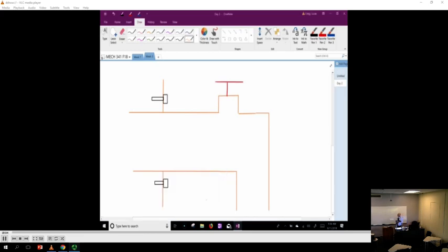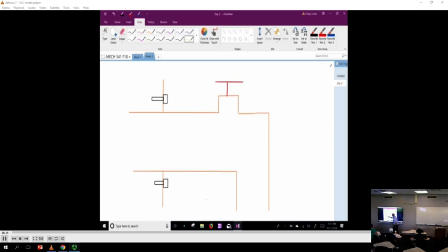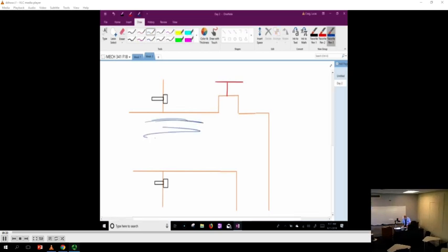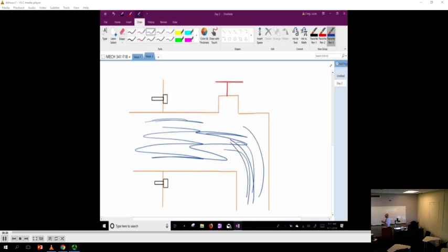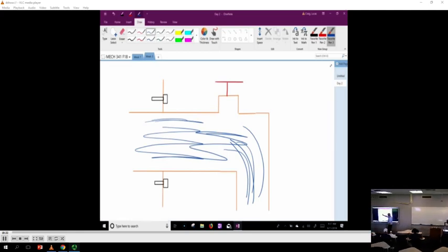this is a water spigot on the outside of your house. Every time I turn mine on, I always think about this, okay? You got bolts holding it in. When you turn this on, water's gonna shoot right out, right? Depends. We can figure out, using this linear momentum analysis, okay? Throw some water in here. How to size the bolt, what forces you need, right? So as long as you understand what forces are required to hold this in here, then you can go and size the bolts, right?